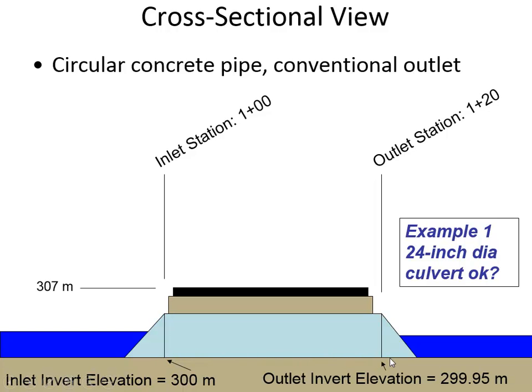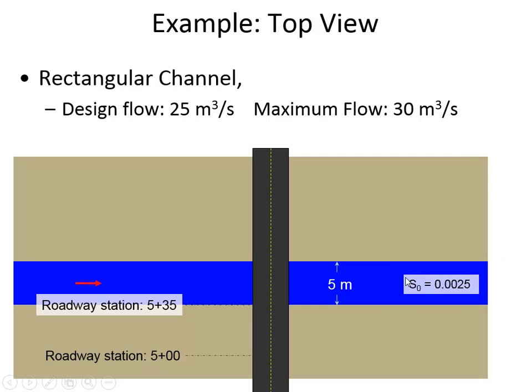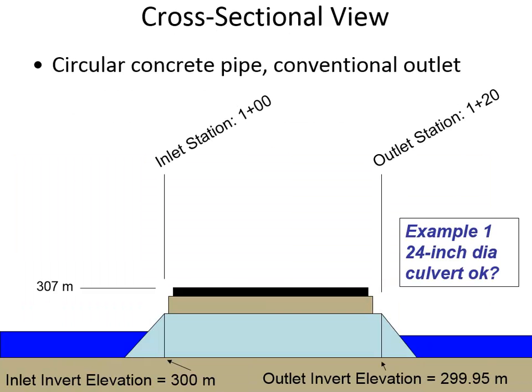To specify the slope of the culvert, we identify an elevation of the outlet. Although we tell the program the slope of the channel, 0.25%, we don't tell it the slope of the culvert directly. Instead, we tell it the elevation of the culvert's opening and exit, and how long the culvert is, and from that it calculates the slope of the culvert itself.